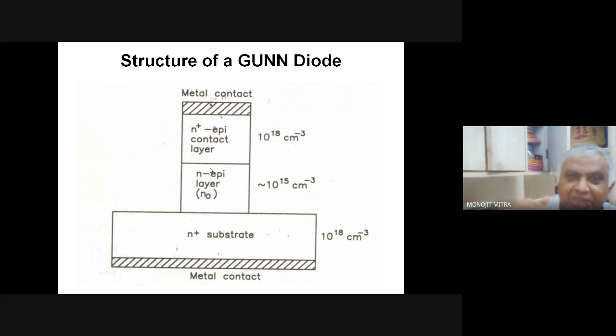Today, by using the epitaxy process, the molecular beam epitaxy machine, you can grow layer after layer, N, P, N, P, any layer after layer. But that technology was not there in 1958 when Read proposed the impact diode. That's why, as you can recapitulate, the Read diode was a theoretical structure, because of the complicated nature of the P plus, N, I, N plus structure.